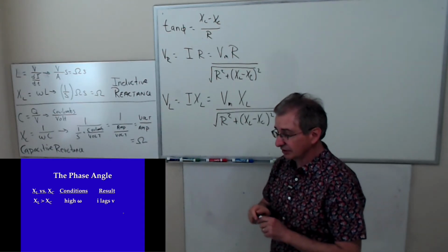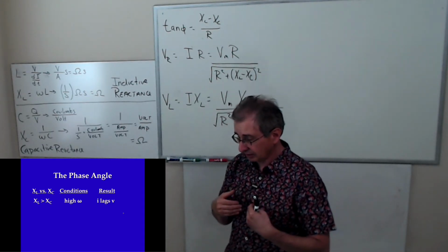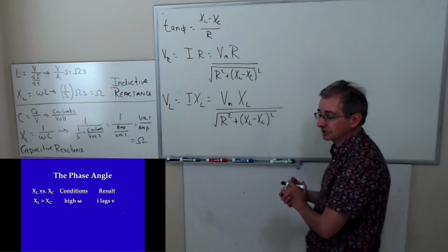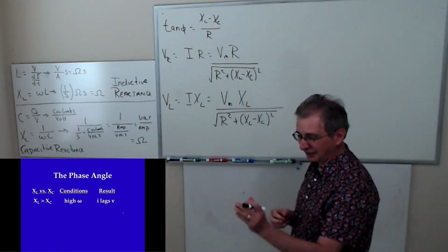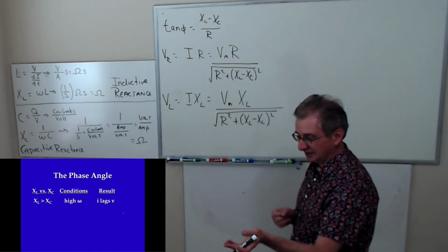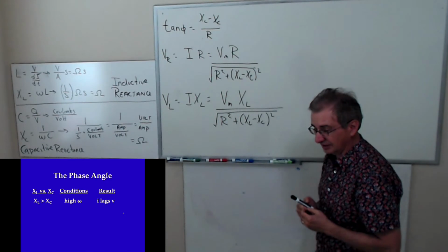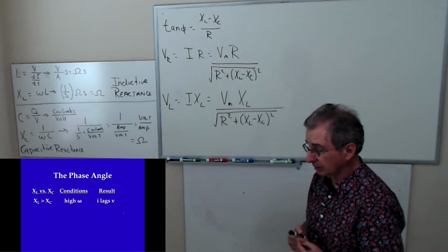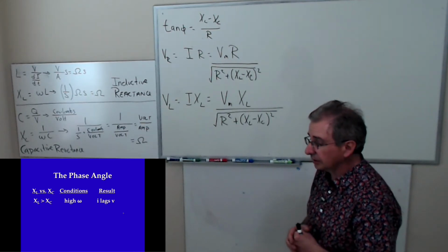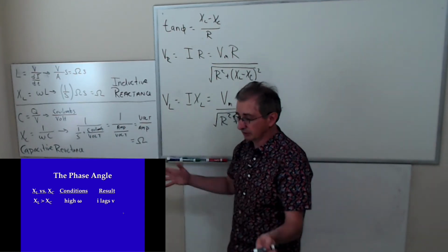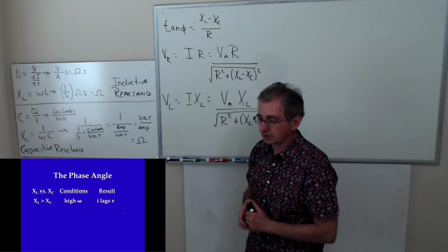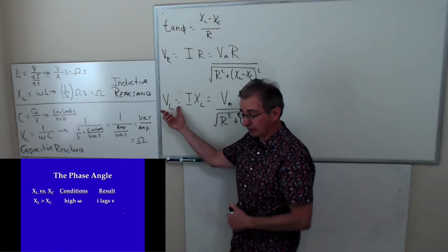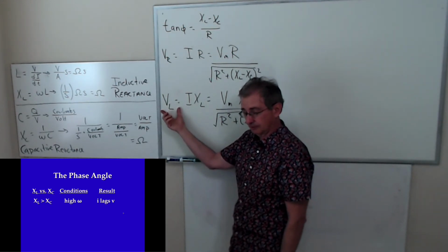And so the phasor diagrams I have been drawing represent the case where X sub L is greater than X sub C. The inductor is dominating over the capacitor, so it's inductive. Does that kind of answer your question, Ratesh? Yeah, it is just that I cannot physically see what that means in the circuit, how the circuit behaves, like as if the capacitor was not present. It just means that the voltage across the inductor is bigger than the voltage across the capacitor. That's all it means, right? Because it plays a more dominant role in the circuit. This will be bigger, and at lower frequencies, that's going to be the case.